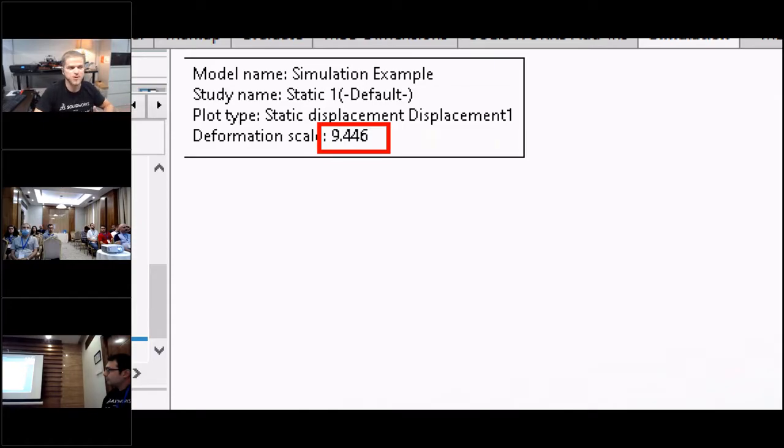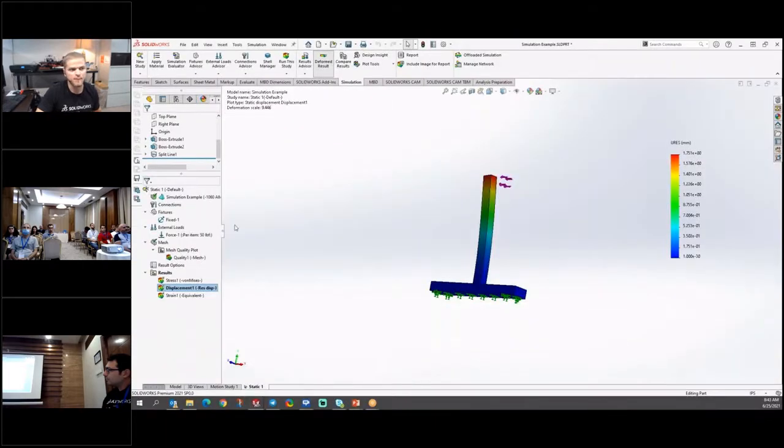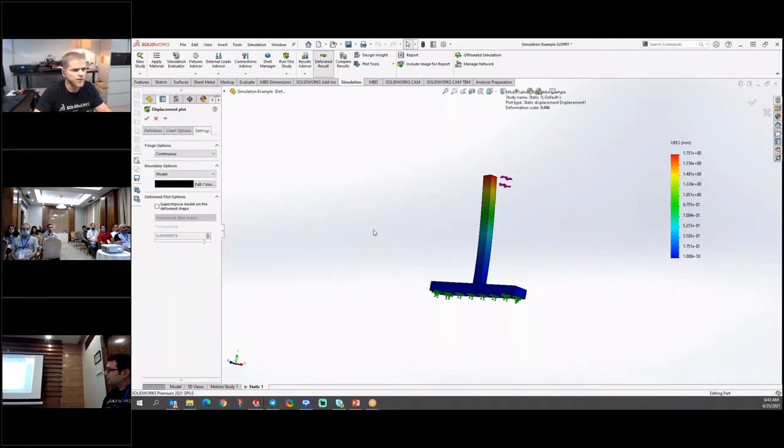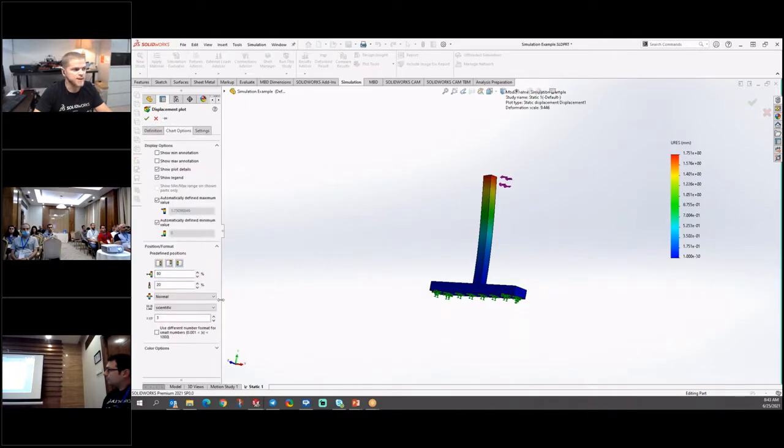So it's having to scale up that motion a whole lot more to show you that same movement. And the point of that movement is really just for you to say, yeah, that's deforming as I would expect. It's almost validation for you, letting you know that you applied your forces correctly, you fixed the model in the right spot, and everything looks correct to you there.